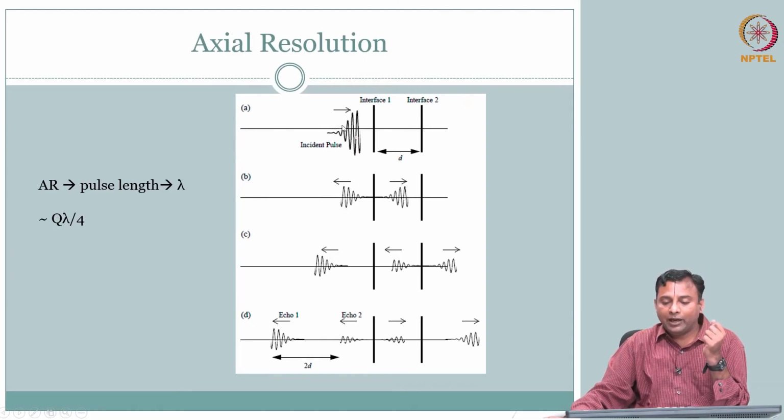So clearly you have this pulse, it is getting reflected, right. This is echo 1, it is getting reflected, this is your echo 2. Of course, echo 1 and echo 2 are separated in time because the interfaces are separated in distance, right. So if you do that, you are receiving this echo. So now your objective is, from this received echo waveform, which you get continuously with the time, right, you have to say whether these two are coming from two different interfaces.